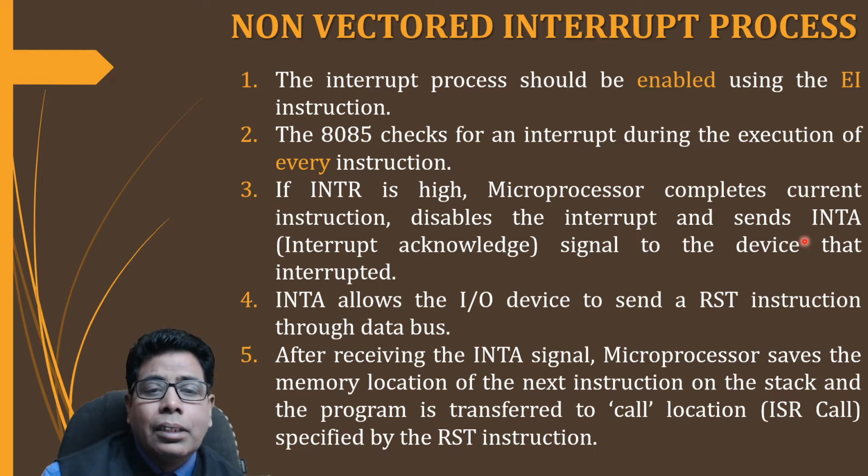Now you have to understand this. This RST instruction is nothing but the restart instruction, which gives the vector address to the interrupting device.